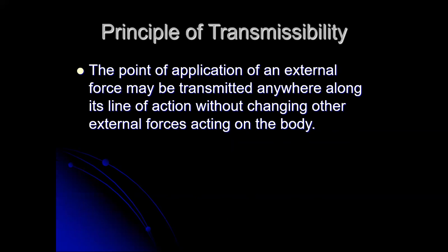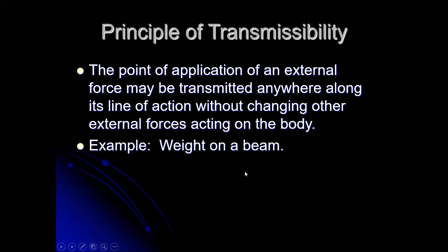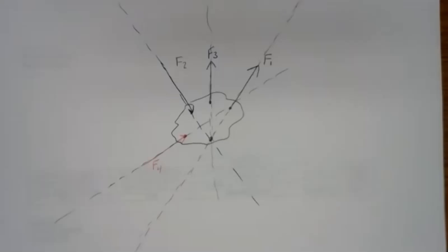We've got push forces, compressive forces involved. It's a lot easier to draw that as a pulling force. It helps us to get the angles worked out properly and to visualize the system better. The principle of transmissibility is just acknowledging that we can move those forces around as long as we keep them along the line of action. So we'll take a look at a couple examples of that just to get the basic idea down.